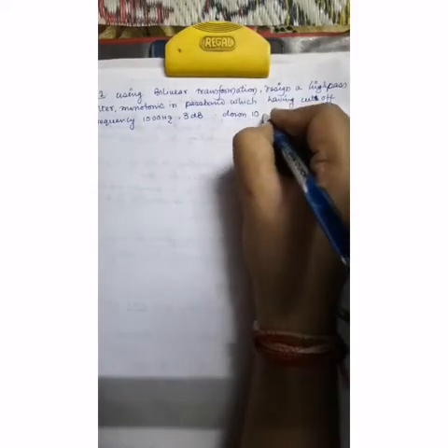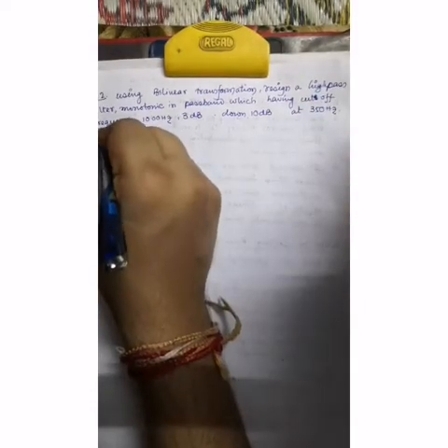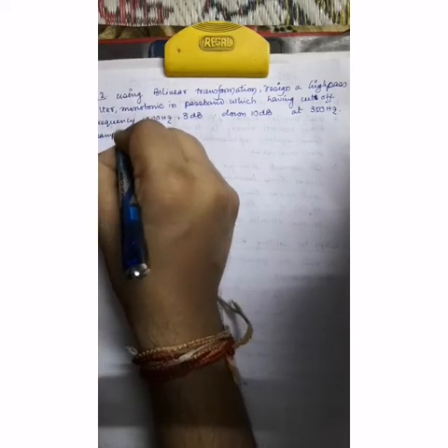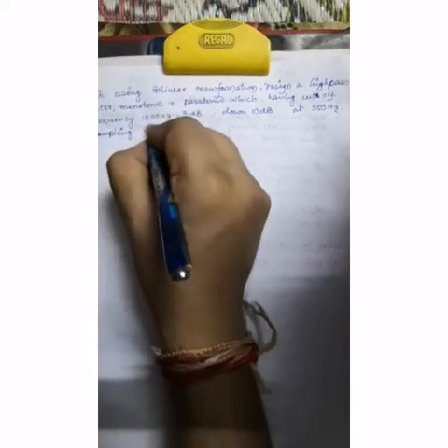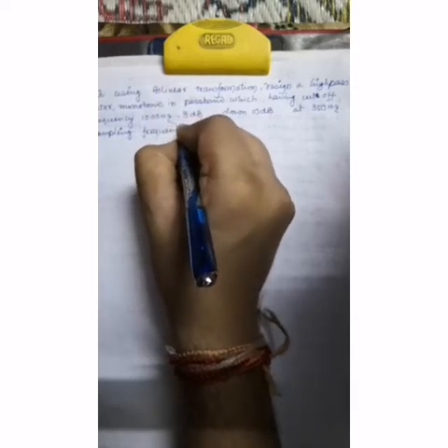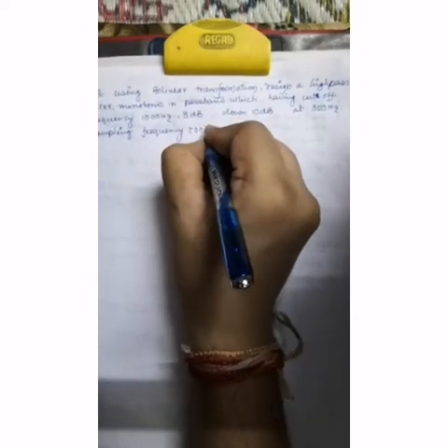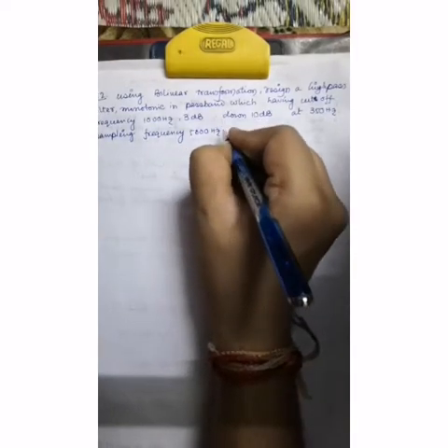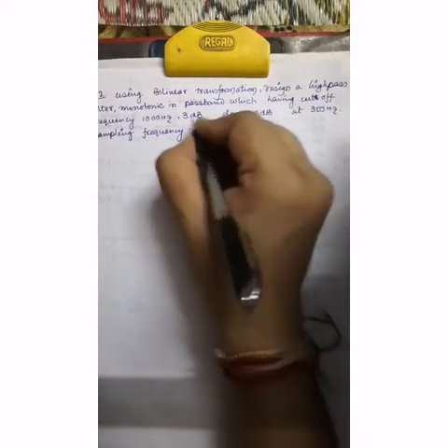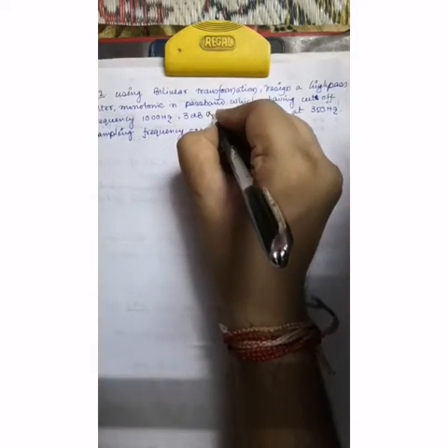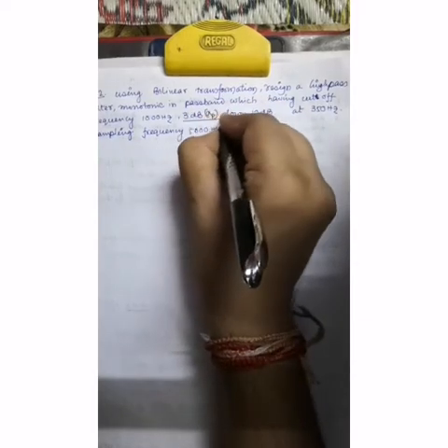Down at 10 dB at 350 Hertz. The sampling frequency is 5000 Hertz. So this is a problem. You have to keep in mind that 3 dB is our alpha p, and 10 dB is the alpha s. You have to put the values.